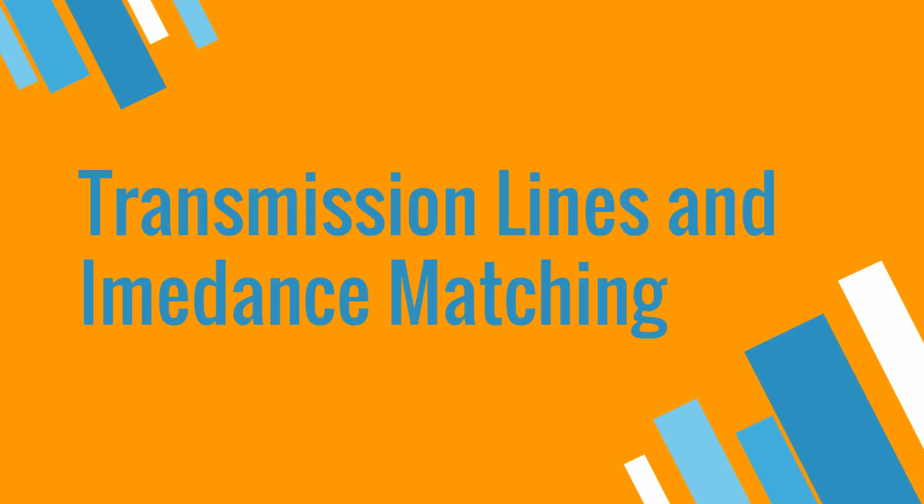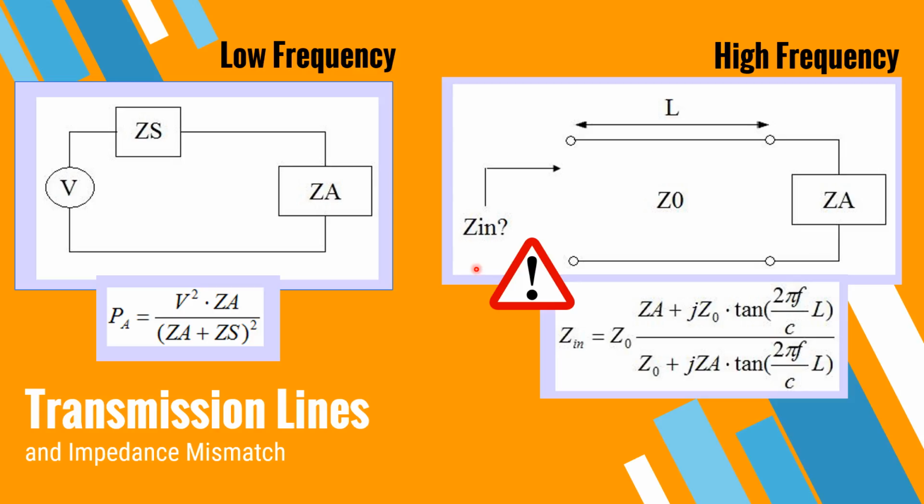Now that we have a general grasp on antennas, let us look at their operations at different frequencies. Antenna performance relies heavily on their impedance along with the transmission line. Antenna impedance relates the voltage to the current at the input of the antenna. An antenna with a real input impedance, meaning a zero imaginary part, is said to be resonant. Note that the impedance of an antenna will vary with frequency. If the impedance contains a partly imaginary number, it will reflect power back to the source.